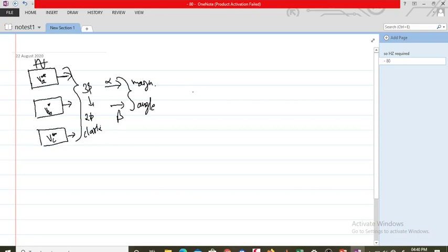But first, let me discuss the concept behind it and summarize again the basic concept of SVM. You have to generate one more signal, which is the triangular wave signal, like a carrier vector, and you should be aware of the sampling time, the TS, and the modulation index where you are operating.